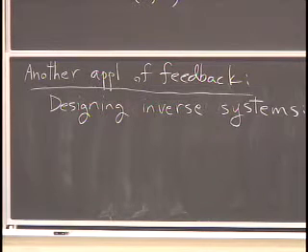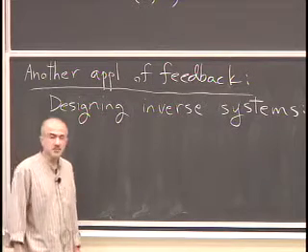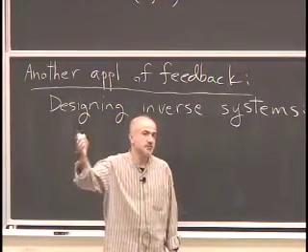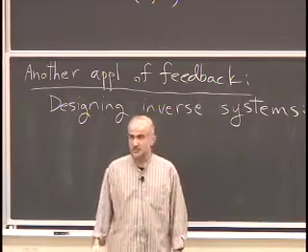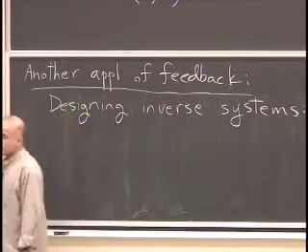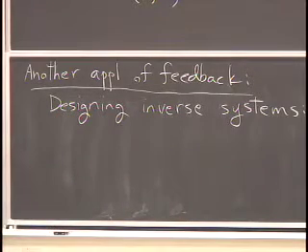But suppose sitting at a particular location, you have a model of what happens to my voice before it gets to your ear. And suppose we simplify everything and model that process with an LTI system. So I speak, my sound goes through an LTI system. What you hear is the output of that LTI system. So that LTI system is the model of what happens in the room. But you want to hear something as close to what I'm saying as possible. So you want to have a system right before the sound goes into your ear that would undo what the room has done.